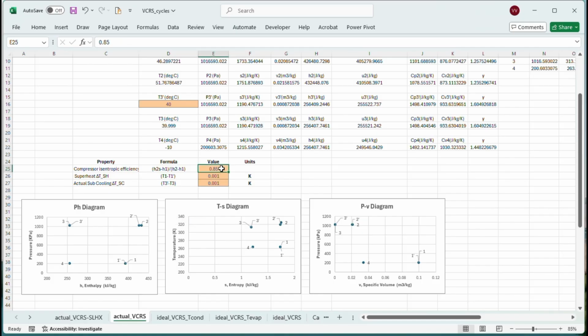Typically the best compression is assumed to be isentropic, but that's not really true. If you could actually lose heat while compressing, that's the best way to compress. Isentropic compression means there's no way to lose heat, but it is typically used for analyzing any system. It gives you a reference point. It makes modeling easy if you assume a percentage over isentropic compression to be your actual compression.